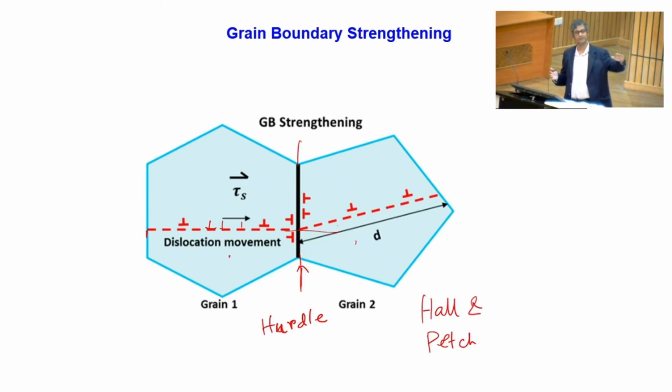And if the person standing at the front moves a little bit, the line will move in the backward direction. That is what is known as a back stress, right? That means the first person is pushing the back a little bit, that gives a back stress to the person behind him. And the same thing gets percolated down to the person at the end of the queue. The same thing will happen here also. So dislocations getting piled up in the grain will apply stress on the grain boundary.